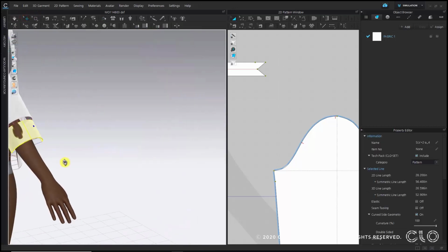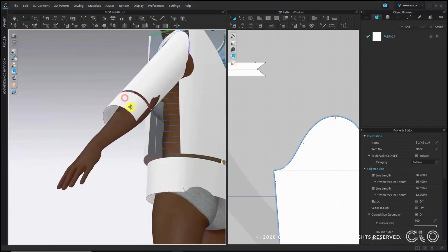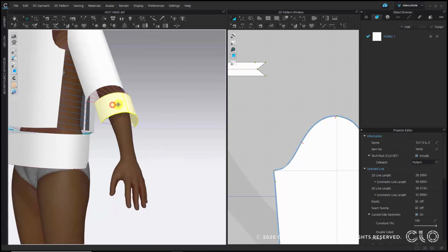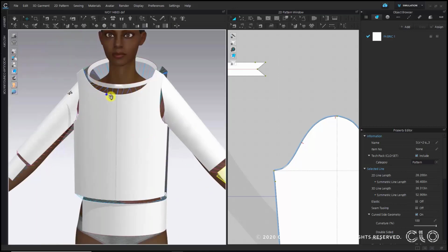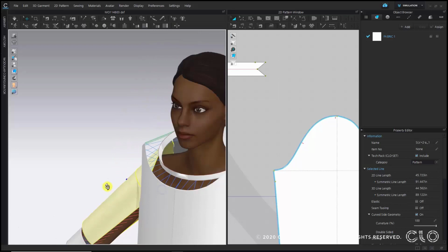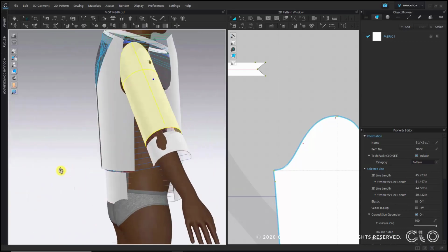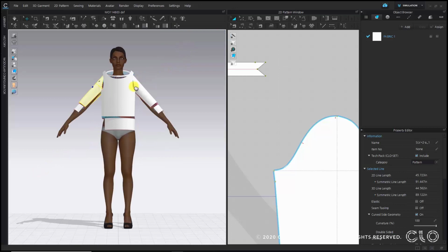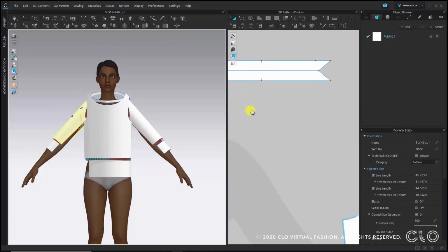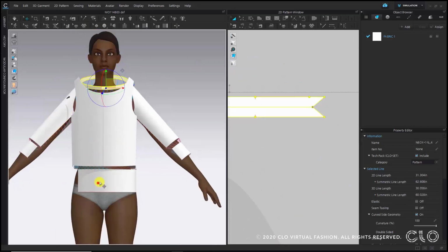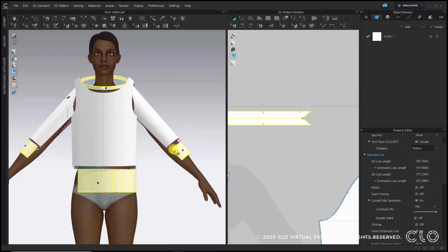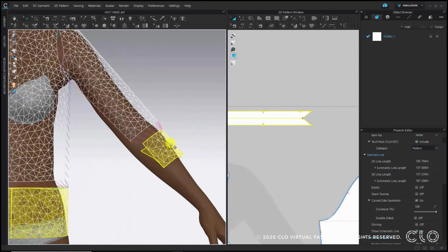Then choose my select move tool, rearrange the pattern pieces a little bit so it won't cause too much intersection when simulating. And then if I go around, I see everything looks correct. No seams look reversed. You would see directly when the threads look crossed. Also looking at the neck, the hem and the cuffs, all of these pattern pieces are double layered. And if I don't tweak my particle distance a little bit, the left fabric side of the inside would poke through the outside. So I can just make sure that I also modify my mesh, just turning this on in the mesh view of my toggle bar to show you the difference.